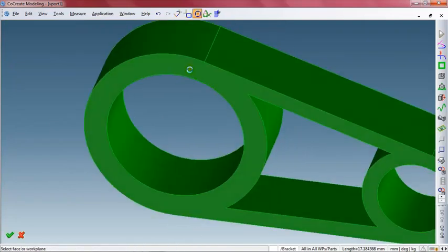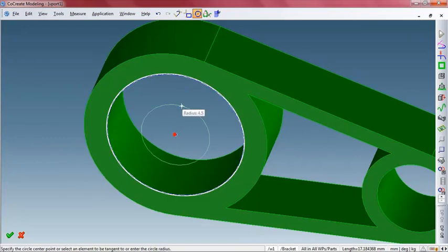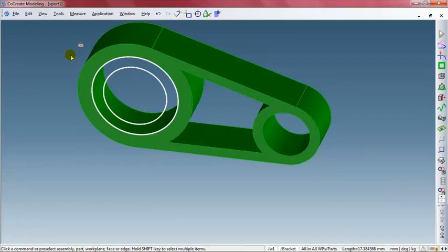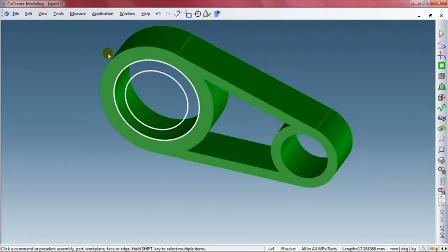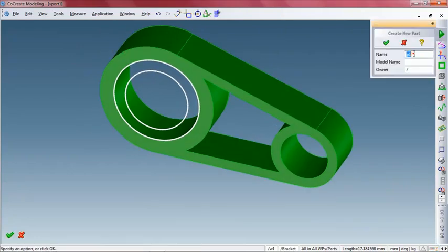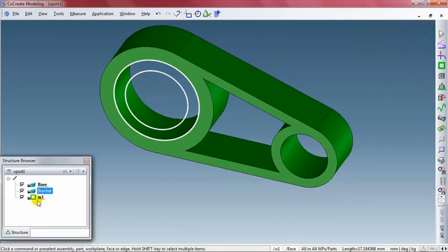Now I'm going to create another part called base in context with the first part. I don't remember the depth of the bracket, but that's okay, as I will just snap to that back face of the bracket. I now have two parts, the base and the bracket, and can add additional geometry to continue to create the base part.